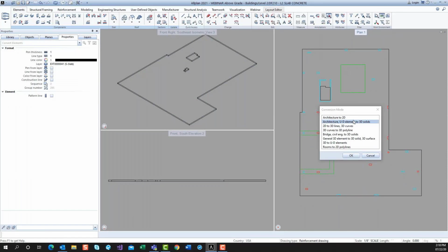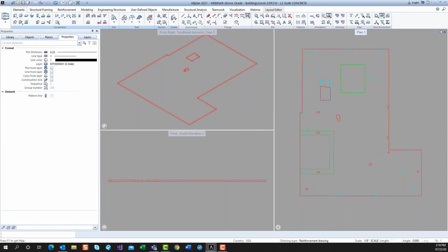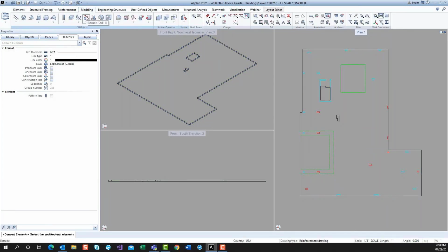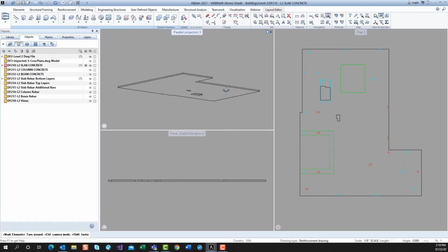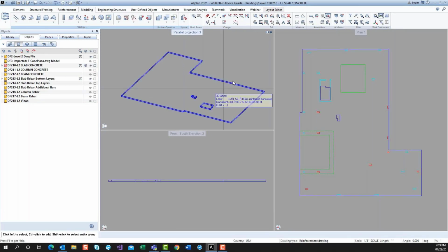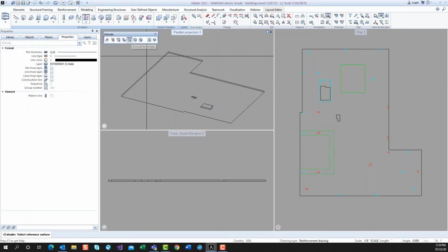A couple of other things we have here is a recess, which is your upper green rectangular area. We also have a little step in the slab, which almost lends to incorporating a beam there as well. In this next portion, I'm going to define the recess as well as the step in the slab, working off of what's existing. The tool I'm going to use is what we call our extrude tool. With the extrude tool, we can use existing faces on our 3D objects to enhance that 3D object. What I've done here in the projection view is zoom up underneath, because I'm going to need to look at the bottom face as well as the top face of this 3D object.